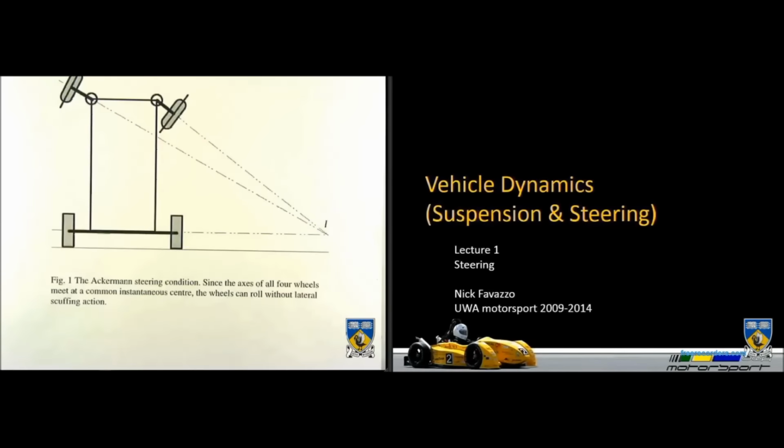Back when they had quite thin wheels, they'd cut into the gravel pretty easily, so it was of pretty high importance back then. Nowadays, the benefits of it are elimination of wheel slipping or tyre scrubbing, and it also reduces steering effort because you're not trying to push the tyre across the ground. The benefits of having non-Ackerman I'll go into a bit later, but the design of such is always pretty important as well. But at the moment we're just focusing on pure Ackerman steering.